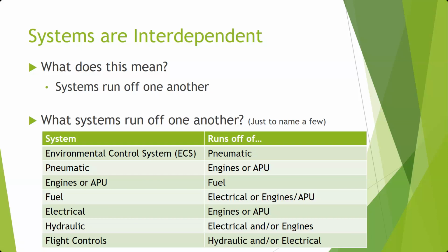But if you're going to flip a switch, move a flight control, move a handle, move a lever, what's going to happen on the other end? Not just on that system, but everything else that it ties to. Like, yeah, I'm going to flip the hydraulics on. It'll get a little bit loud. We'll make some pressure. Right? As long as no one's in the hydraulic bay, we're good to go. Except if somebody's out there doing wing rigging and now the flight control moves on them, right? Flight control rigging. So keep that in mind for safety as well as for things like troubleshooting and operation. Okay.